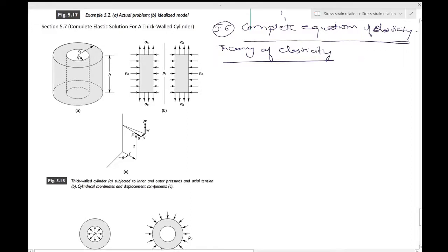So if you have this elastic body, three-dimensional, and you have so-called mechanical loads, you have displacements, and you have a thermal loading, you would want to find the distribution of stress and strain in this solid, meaning if this is your origin, then you should be able to point the stress vector and the strain vector at any point of this solid.